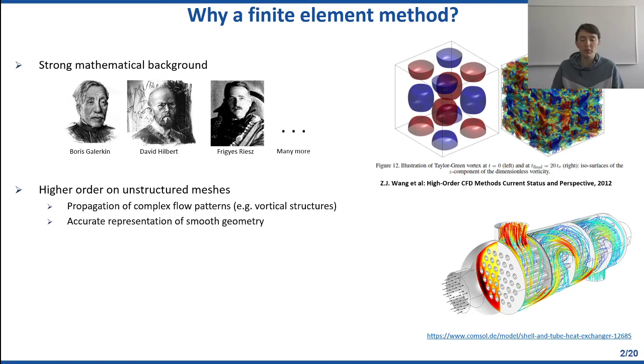And it turns out that for fluid mechanics, it's actually very important that we use higher order methods, because we have all kinds of interesting flow structures, vortical structures, certain eddies, that we'll talk about in later lectures. And these need to be represented, and represented well, in order to be maintained throughout time, because else they will dissipate too fast, they will disappear, and these actually have a huge impact on the complete solution field. So higher order methods are particularly important for fluid mechanics.